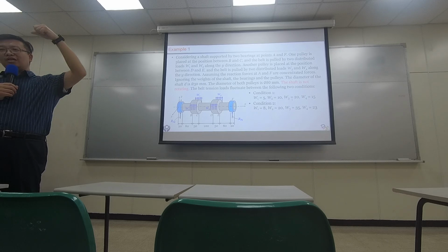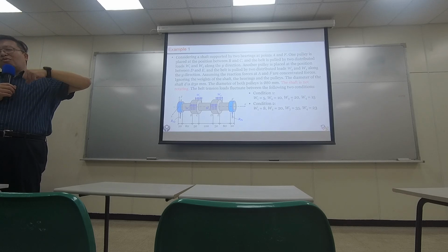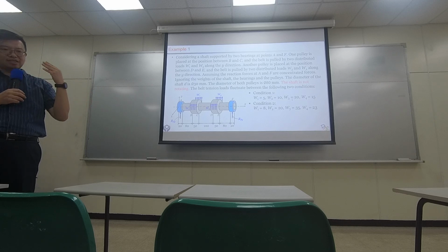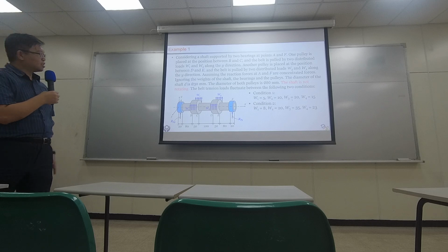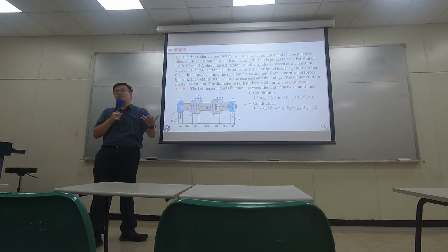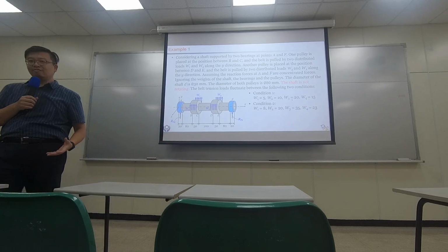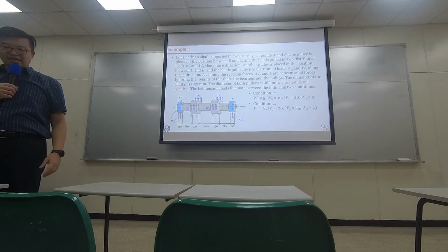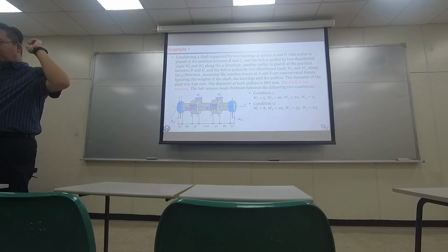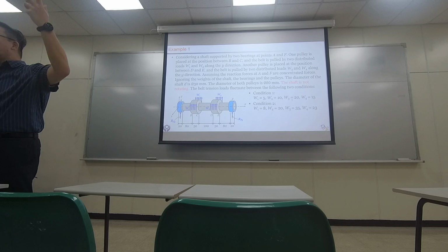So maybe there is a periodic motion that is constantly changing the tensile force within the belt. That could be happening if you have some kind of mechanism that is not doing exactly the same thing for the entire cycle.